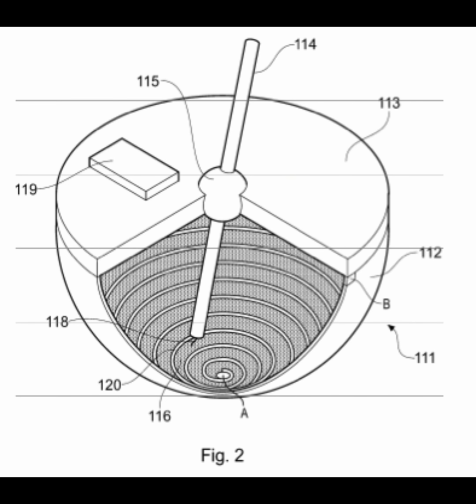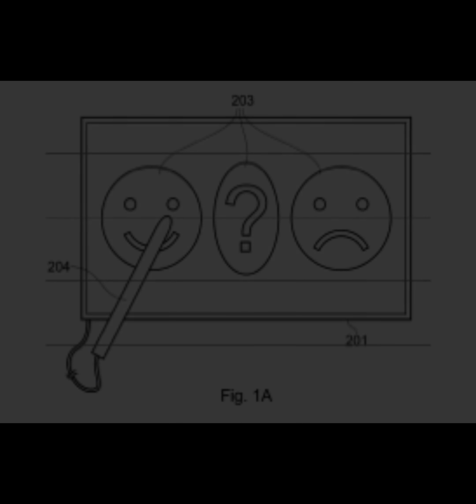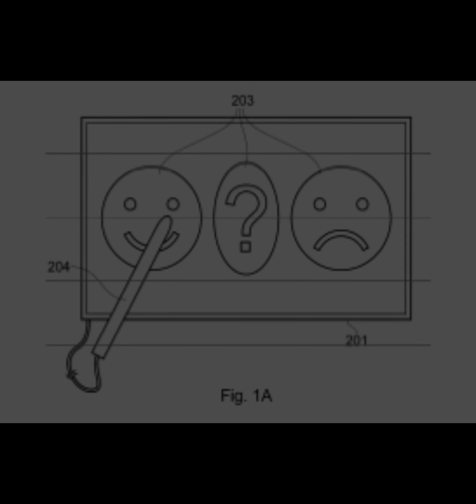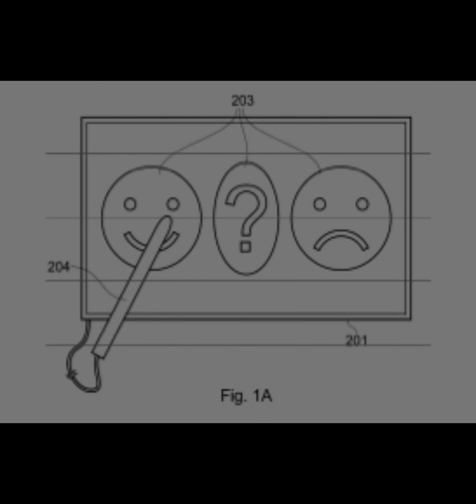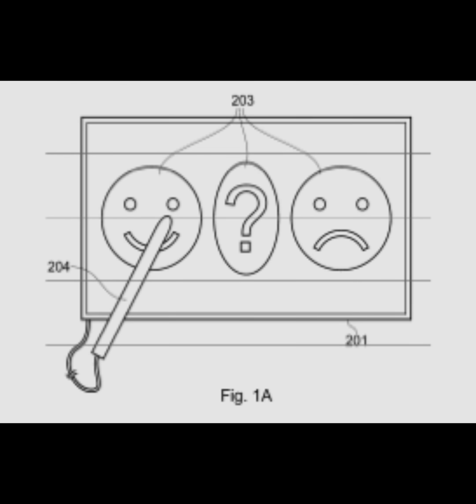The actuator, 104, comprises a conductive element, 108. The conductive element, 108, is in contact with the resistive layer, 106, and picks the voltage off the resistive layer. The actuator is configured so that the conductive element can slide along the band between the contacts A and B. Because the voltage varies linearly along the band, with distance to either of the contacts, the position of the actuator 104 can be derived from the voltage picked off by the element 108.